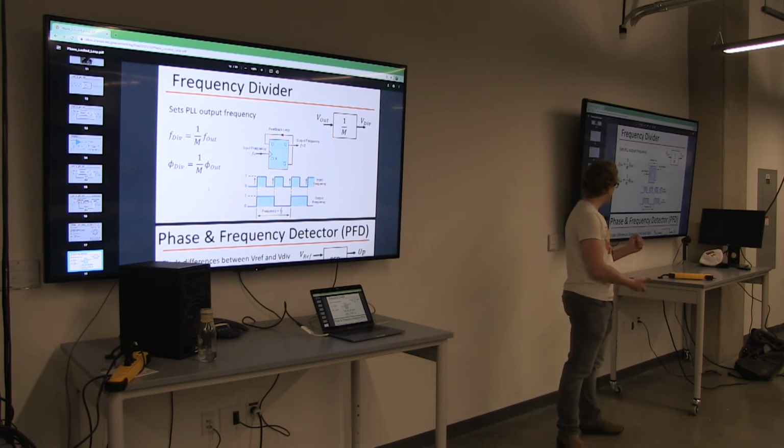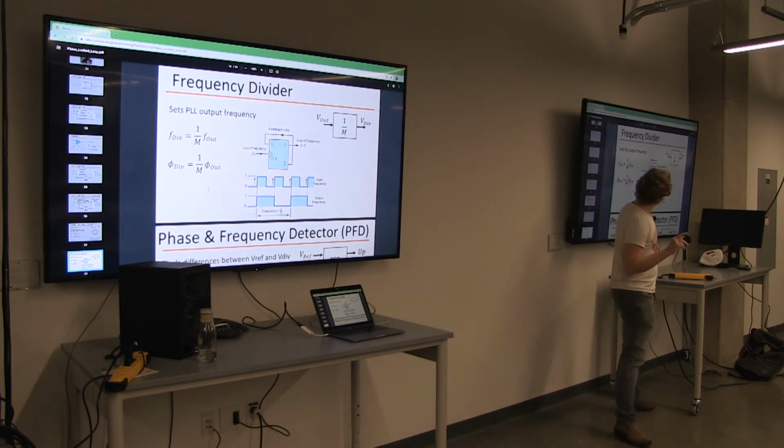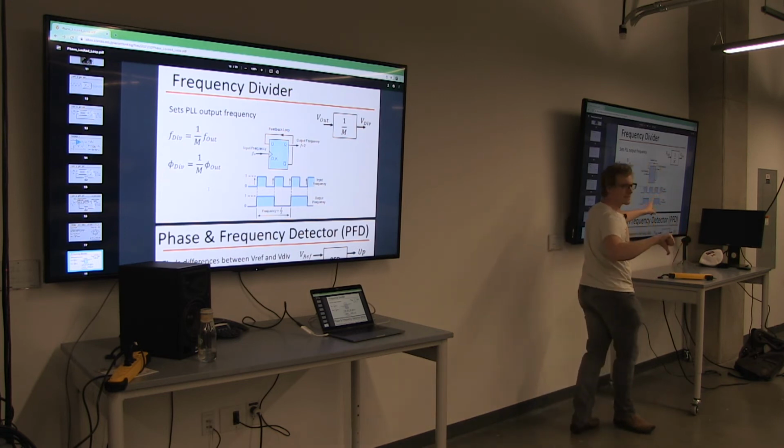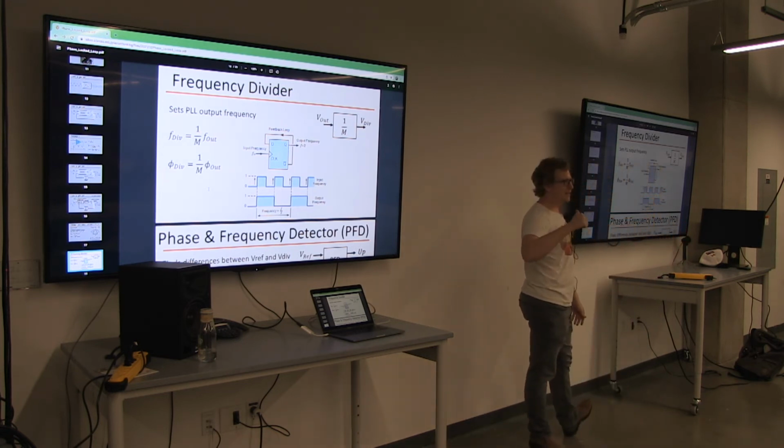Flip-flop, if you have the output feed back to the input, you have one clock cycle that makes the output become the inversion of the last output. So QD is being fed the input. This is the previous output being fed back into here. One clock edge makes it update, the second clock edge doesn't. By missing every other clock edge, you now have half the number of bits on the output, and so you have a clock that's half the speed.